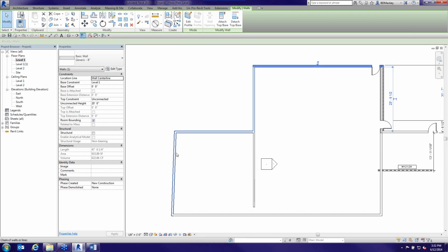That's very cool. Really great for filled regions, for detail lines, whatever you're doing. You can come down here and just hit the tab. And again, here's the other feature. Notice how I moved my mouse to this side of the wall. It grabbed them in a clockwise motion. I moved my mouse to this side of the wall. It's now in the counterclockwise. So even with this feature, if you've got a circular joined, or I should say chained objects, depending on which side of the object, you can get different selection options.